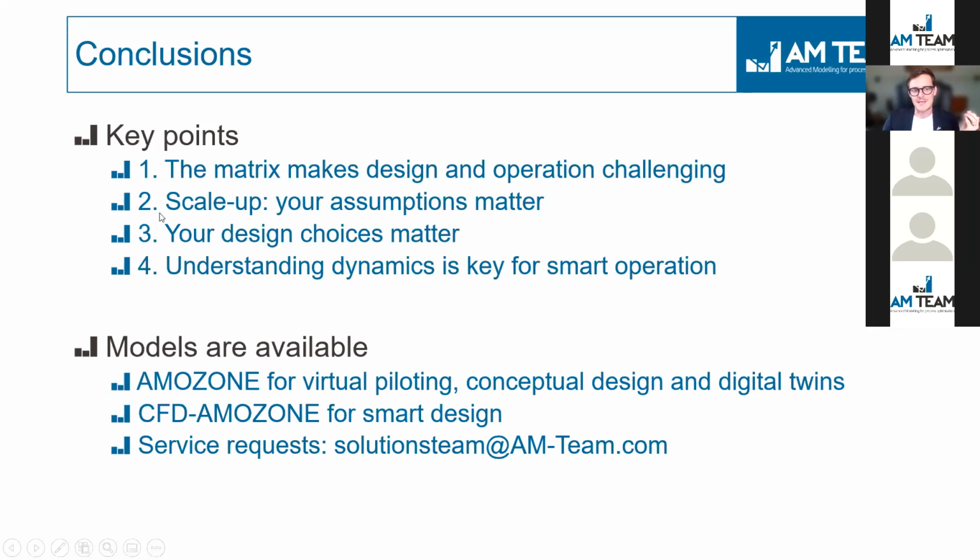Then, of course, the second key point was the scale up. So pay attention if you scale up from batch to a pilot or from a pilot to a full scale, that there are also assumptions in how your design of experiments was, how your experiment was set up. So pay attention to that. It's not only the water matrix effects. So water matrix is your water composition. So also your design. Then if you ultimately decide to build a plant, your design choices really matter.